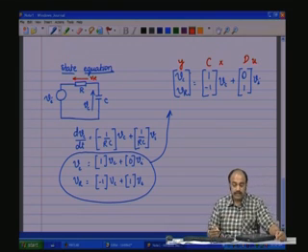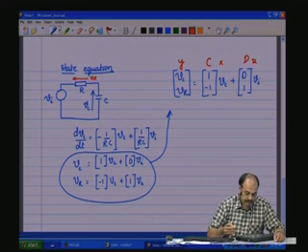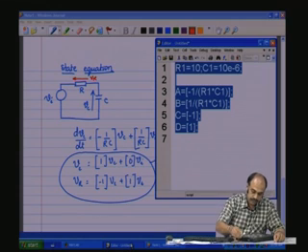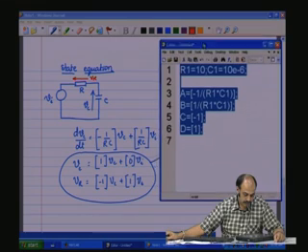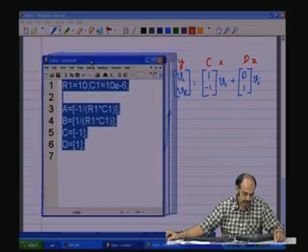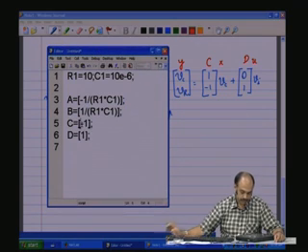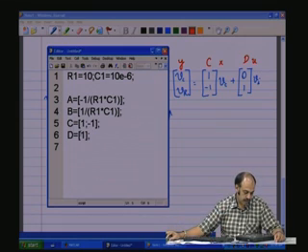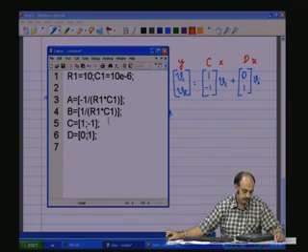This can be easily inputted in MATLAB, and then you could look at all the outputs simultaneously. So, let us go and make that change. So, what do we do here? You see that the C matrix is 1, semicolon is next row minus 1, D 0, semicolon is next row 1.